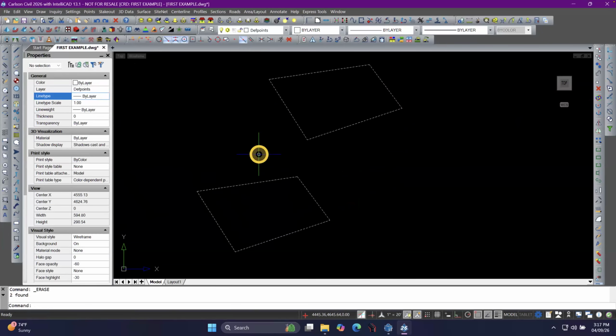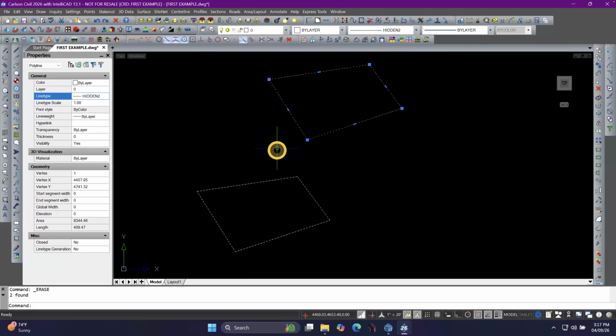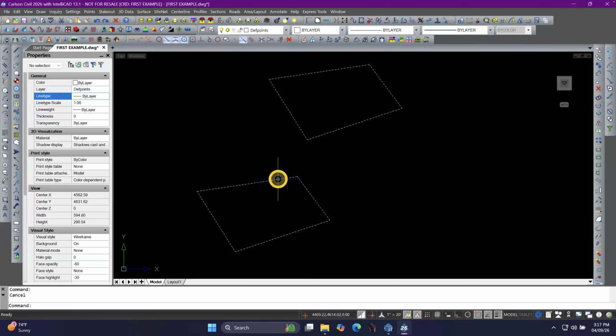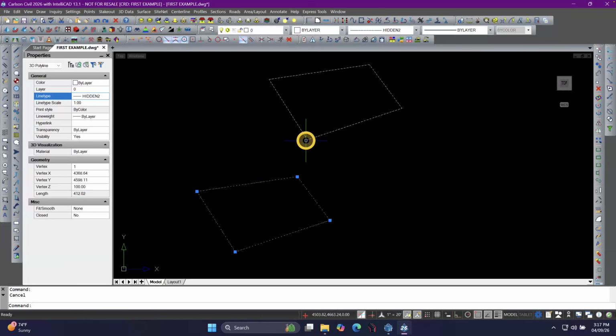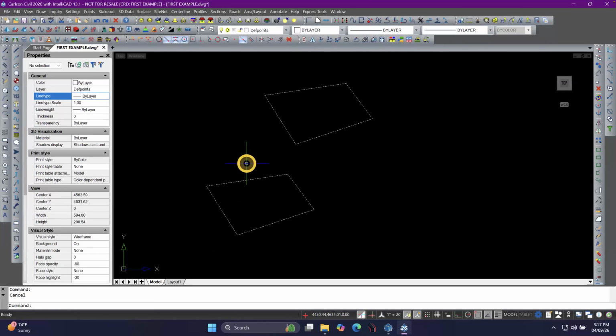So, all right, so now you've seen a couple of things. We've got this 2D line or 2D polyline. We've got a 3D polyline, which is just like a polyline, but these corners have potentially different elevations. They could also be all at the same elevation, but it still would behave as a 3D polyline as far as its definition goes.